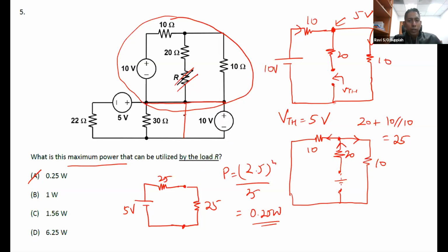But if you were to put another resistor here, it will still be considered as two separate circuits because these 3 points are all connected together still. So effectively this is considered like one separate loop, and this circuit will still be considered separate because of the way it is connected over here. So here you cannot have a straight line, because if you have a straight wire here, you will short circuit this 10 volt supply. But if you put a resistor here, it's still fine.